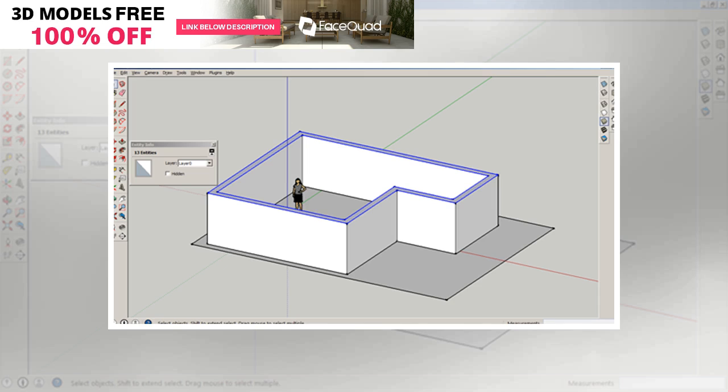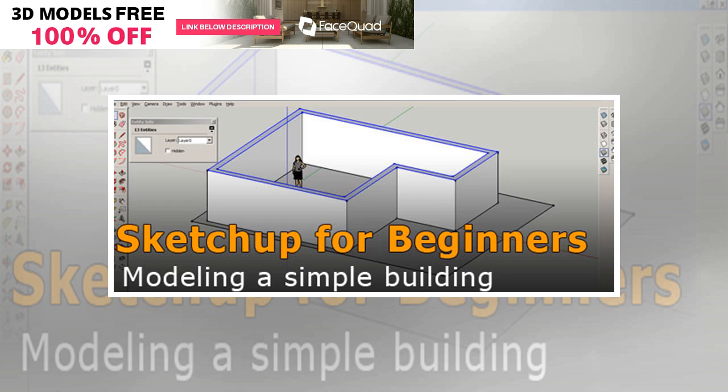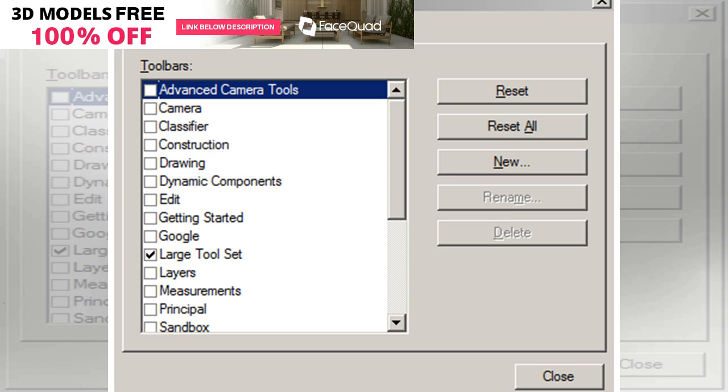Use F to specify the wall's thickness. Select your shape, press F, click, drag and drop, then type the wall thickness to give more precision, for example 300 mm, or 12 inches, and press Enter. If you are okay with approximate dimension, do nothing after you drop the mouse. This technique is common for all drawing tools in SketchUp. Delete the interior part by selecting the internal surface and pressing Del, or with the E tool. In 3D view, use the P tool.